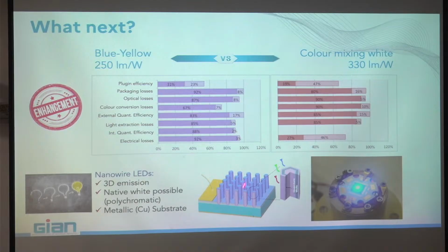The problem is this kind of nanowires, they are very close to each other, and if you want to avoid sparkings, you have to limit the voltage, or you have to put insulating material in between the pillars. But if you put insulating material, you don't let the light come out. The problem is rather difficult to solve. You see here a prototype of such kind of LEDs.